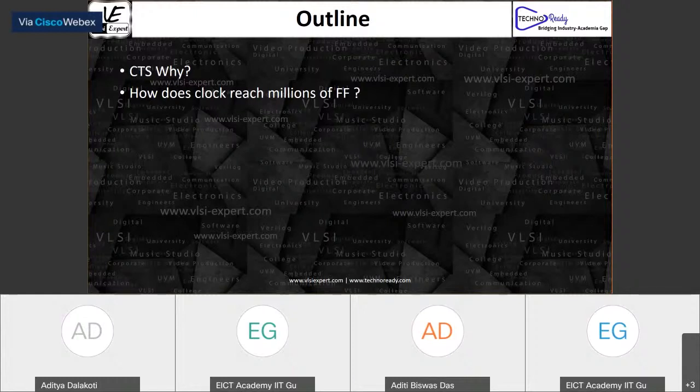Do people understand this? Anyone has any questions or points they would like to add on this? Fewer buffers means less area, less power, but it means you may not be able to transfer the clock cleanly with the noise constraints, basically. There's always a trade-off between area, power versus noise. Noise then boils down to timing.